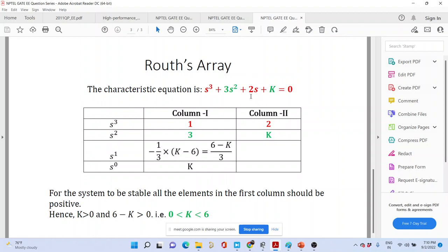Whereas, if you understand the philosophy of the Nyquist plot, what you do is encircle the entire right hand side of the S plane. If you are encircling the entire right hand side of the S plane, then whatever the coefficients be, the criteria will tell you how many closed loop poles may lie on the right hand side of the S plane. So it helps you in that fashion. That is why Nyquist came up with that criteria.